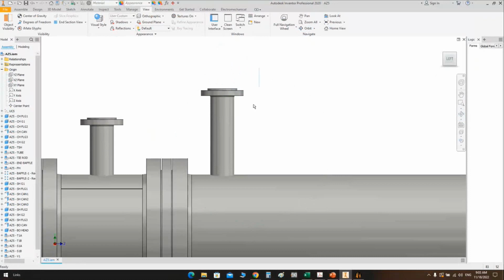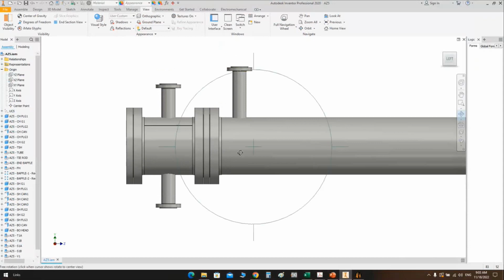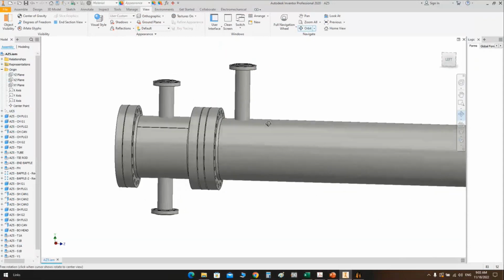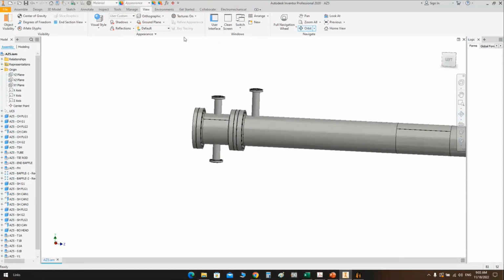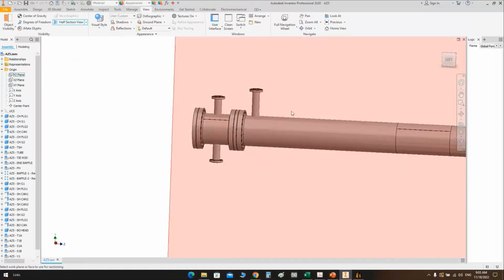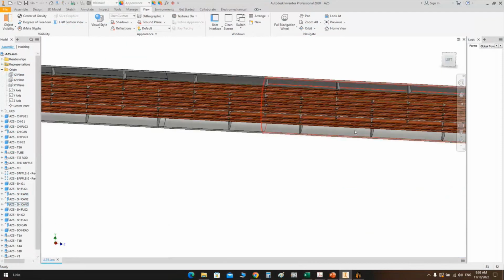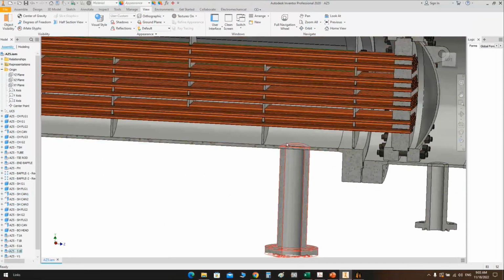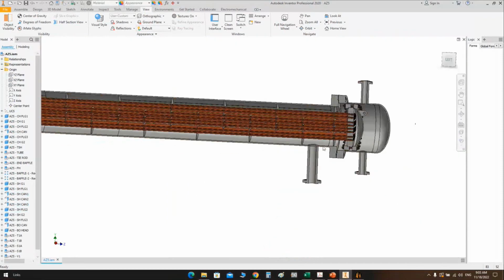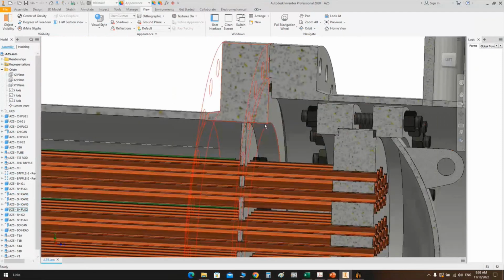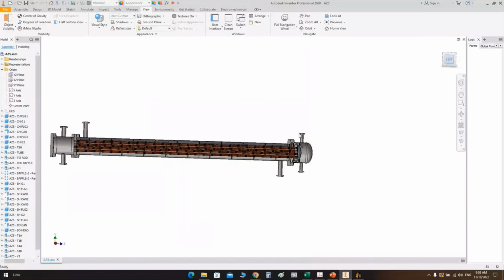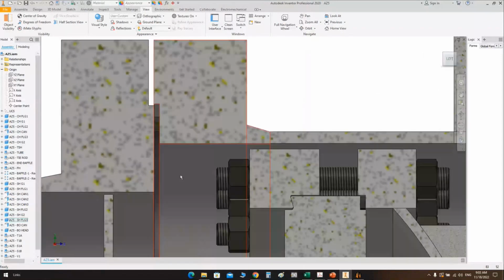As you can figure, this nozzle projection, I defined it as per the mechanical calculation. That may be for some reason, but that's the shape of this nozzle. If we take a half section on the model to figure out the nozzle locations, here it's before the first baffle, and here after the last baffle, between the last baffle and end baffle. Okay, and here the end baffle location, the tube bundle, and we can figure easily that we have a clearance for thermal expansion of the floating head and enough area after that one.